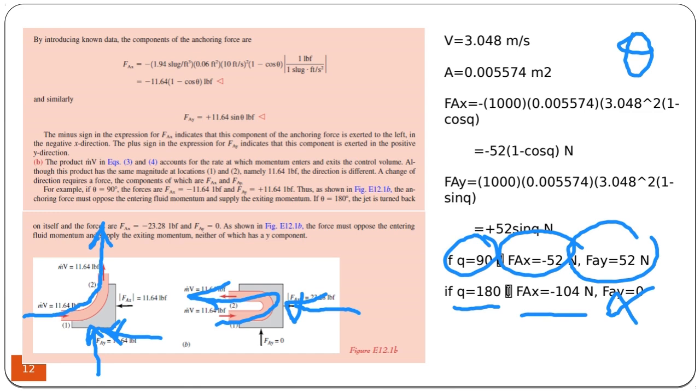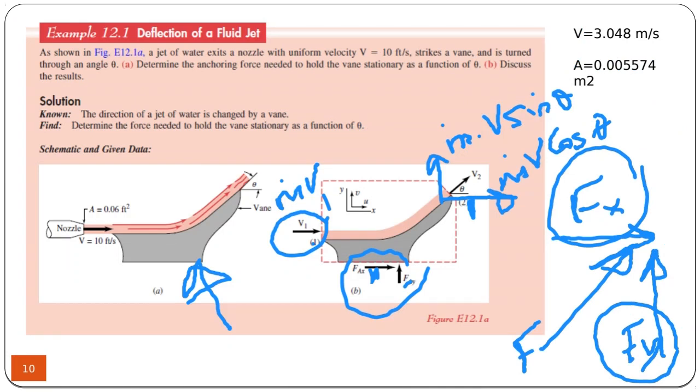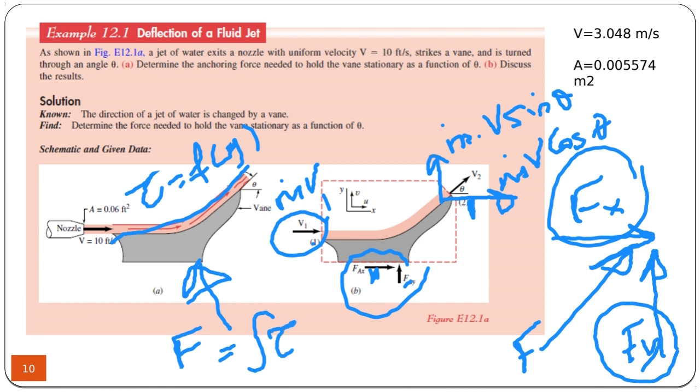How can we apply the friction in the equation actually? If there was friction, it's not so easy, because friction would affect all the faces, all the surfaces, so you should write the shear stress as a function of the path. In this case, the friction force would be tau times dA. You have to have a function of the shear stress which varies with the path. Otherwise, you cannot do it.